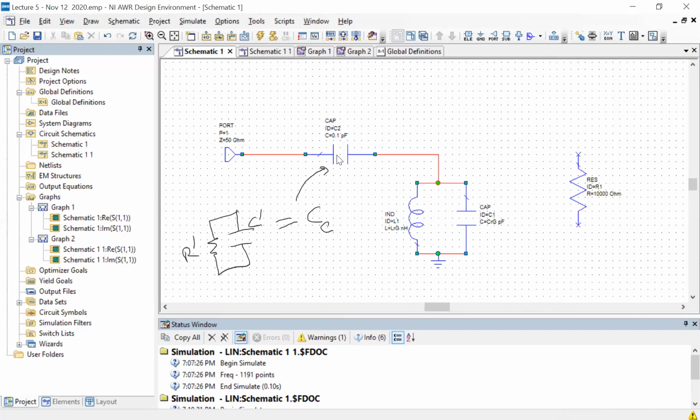And then you will see that by introducing a coupling capacitor, R prime is going to be greater than R, and hence Q prime is going to be greater than the original Q you had. Okay. So this gives you both the reduced dissipation effect and the shift of the frequency because of this capacitance loading.